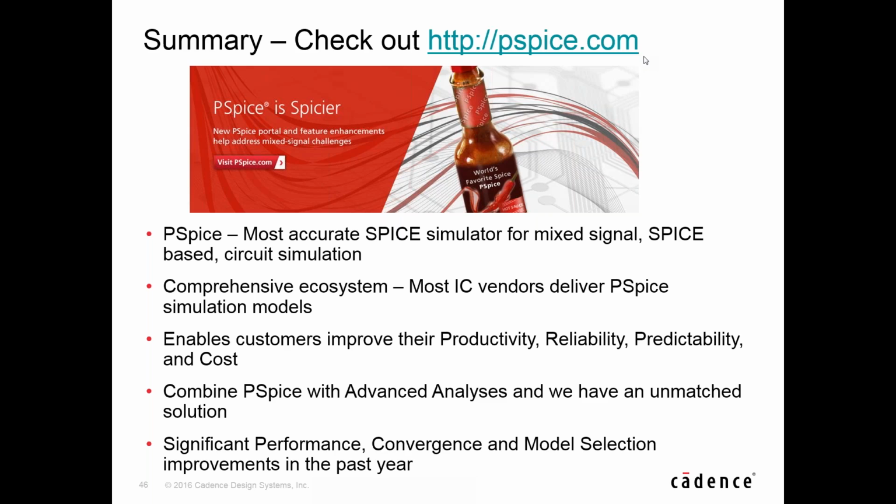So we have one more minute, so I'll ask one other question. I'm interested in finding timing violations in a digital portion of my circuit. Do I need to use another tool for timing budget, or can I do that with PSpice? You can do it with PSpice. The digital functionality in PSpice is actually quite powerful, and now that we've opened it up to other types of models like SystemC models, we're going to start to leverage and refocus on some of these digital measurements.